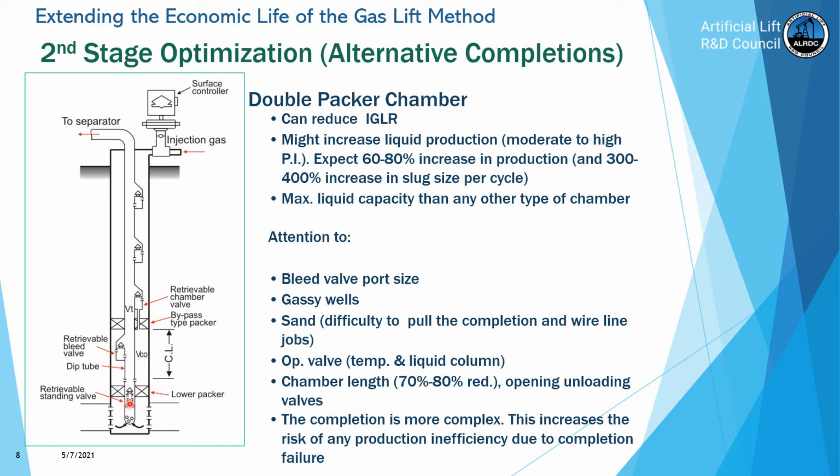And if the well produces a lot of gas, then we also have an arrangement here so that the liquid will have to go first up and then down and then into the perforated nipple. That arrangement will act as a gas separator there. There are a few things that we can do to take care of these two problems.